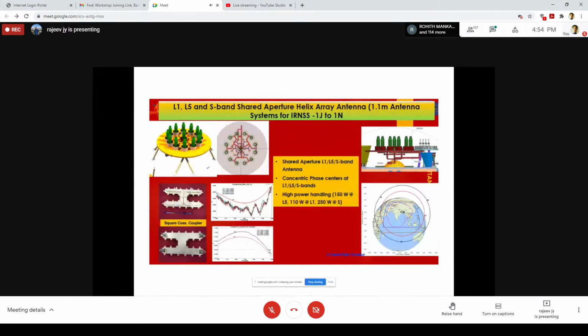So it becomes all the more challenging, because the transmitter and receiver systems cannot be very broadband. There the power requirement, power stability, flatness and the noise temperature of the receiver are very important. So the availability of devices, the pHEMT or HEMT devices, or GaN SSPAs and all those things, availability is the issue for wideband.